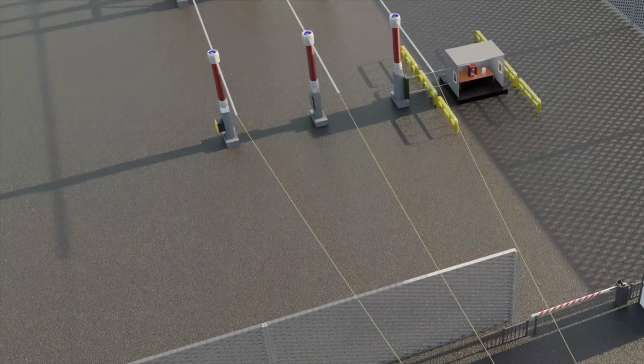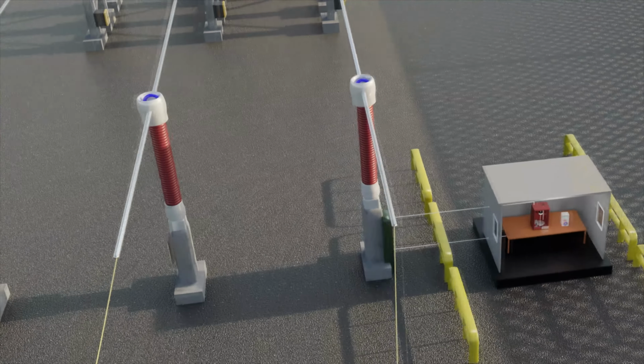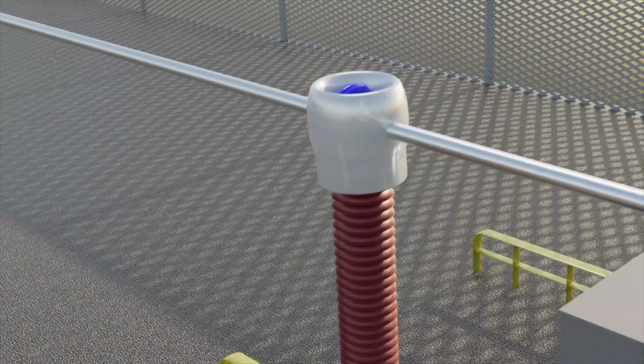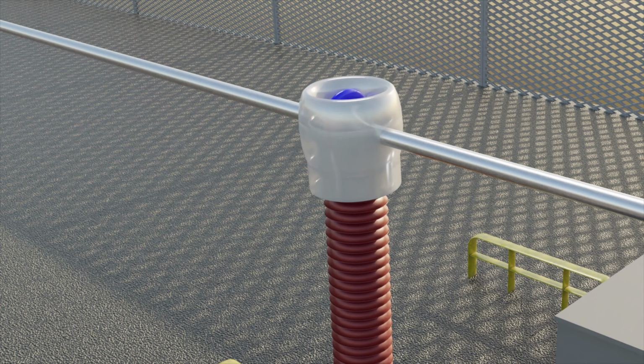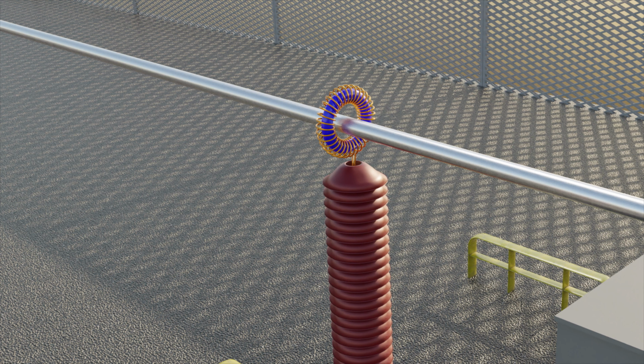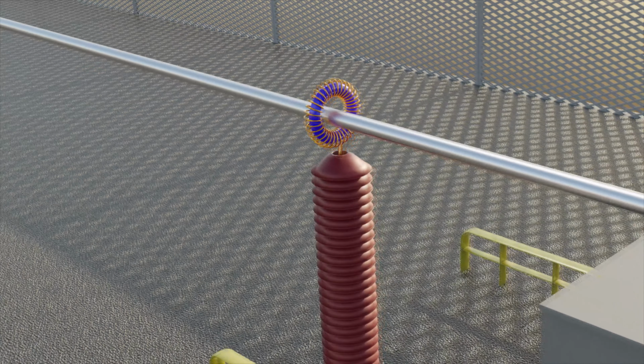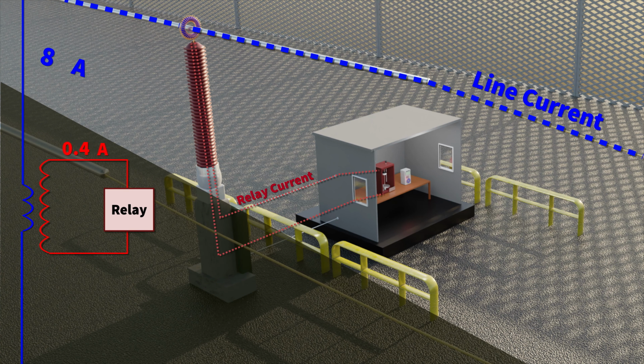The current transformer, or CT, has the ability to step down the current on the line to a proportionately lower level. This is absolutely necessary because the fault current is way too high to measure directly. Now, the CT is very much like a standard transformer, where the line current is the primary, and we can construct a secondary with the number of turns we require to step down the current. Now, in the electromechanical relays, this secondary CT current is actually fed straight into the relay and has a direct effect on its operation. More on that a bit later.